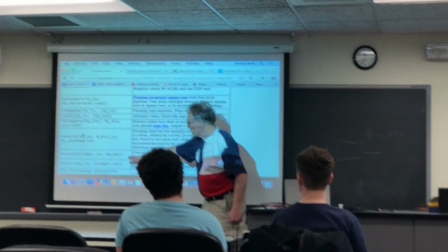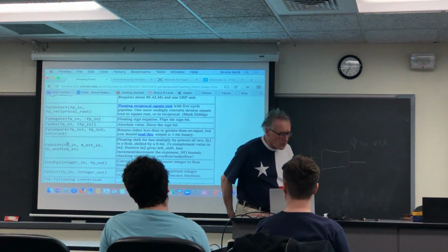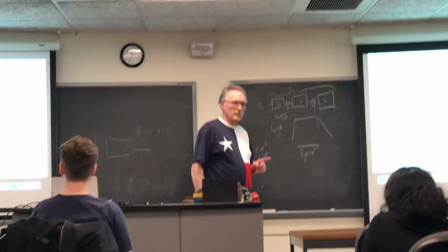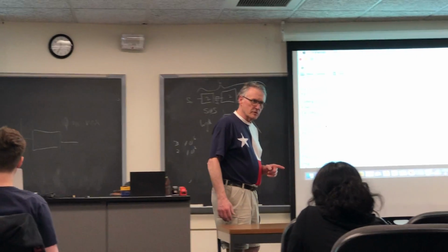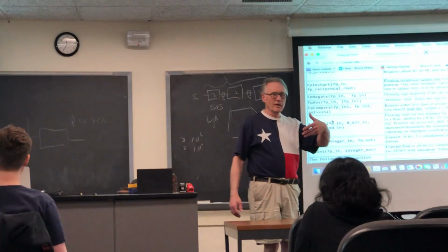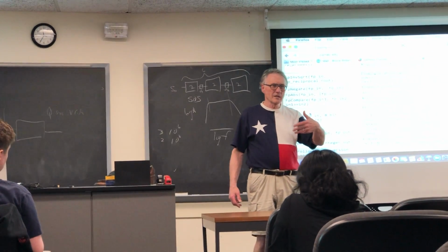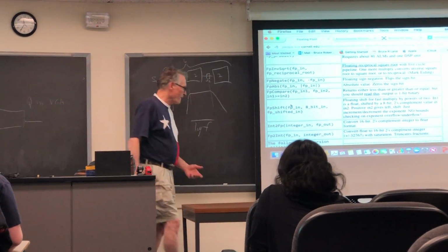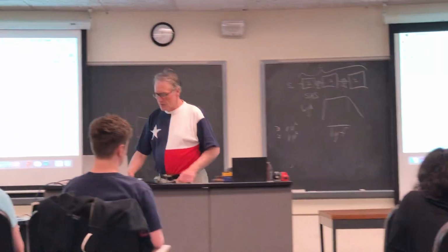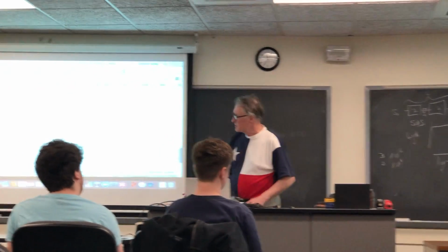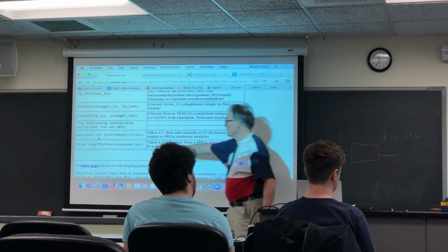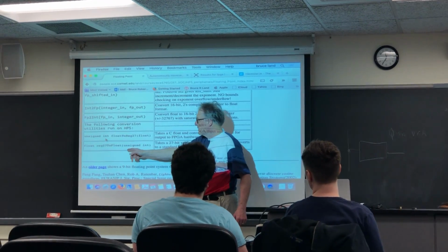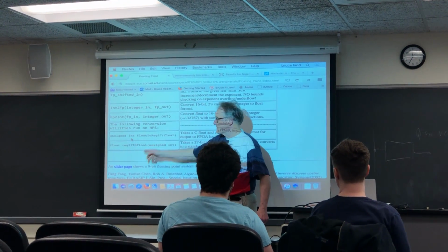And there's integer to floating point and floating point to integer, so that you can output audio, because the audio codec expects integers and produces integers, has integer output from the audio ADC and takes integers in to produce audio back through the DAC. But there's 2 routines that also run on the HPS, which convert a float to this reg27 internal format, and take the reg27 format and convert it back to a float.